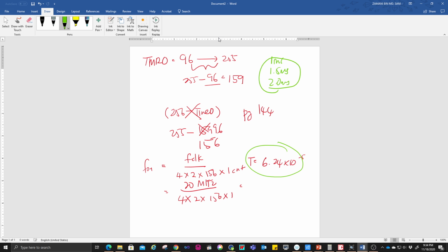You can try here. Okay, I just want to show you on the servo motor. This is the last one. So the rest of the examples you can look at in the book, right? You have to find out the values over there. So for the servo motor, you can go back to the module at page 87. That one is quite confusing on the code because it relates to port A. So I don't want to use port A at the moment because port A is always reserved for the A2D modules. So let's try to change it to port B.